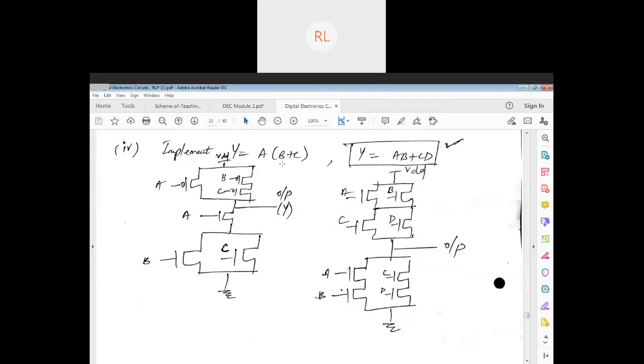Okay, fine, thank you. So questions can be asked on anything, such as y is equal to a into b plus c, or I can even ask a into b plus c plus d plus e. Now I will tell you one trick. Just count how many parameters are here: a, b, c, d. You should have two times that number of transistors. So I have a, b, c, d, which means four different parameters, into 2, so 8 transistors: 1 2 3 4 5 6 7 8.